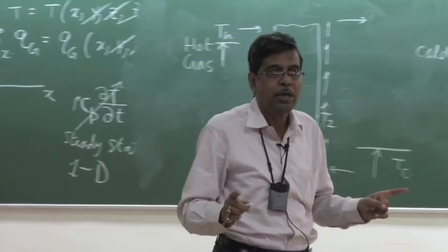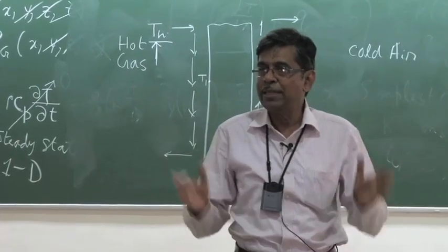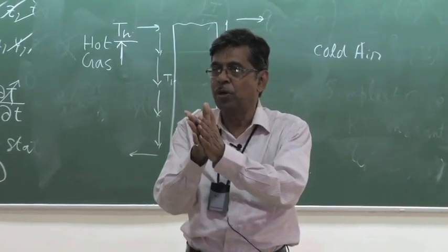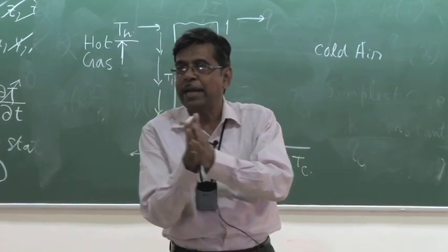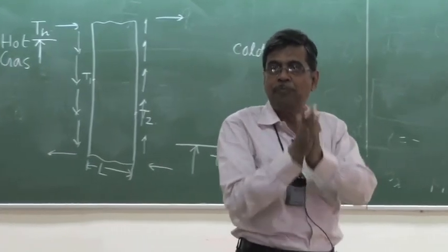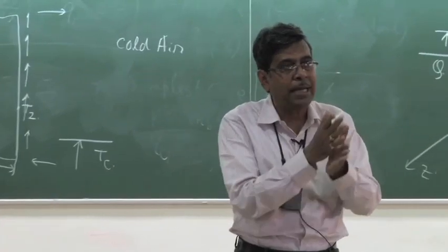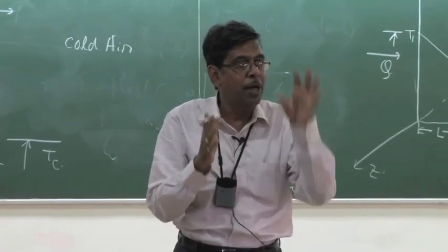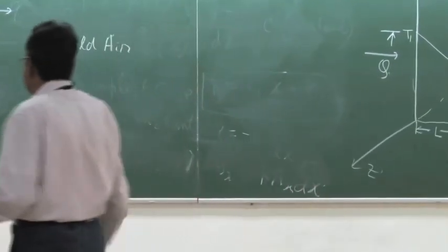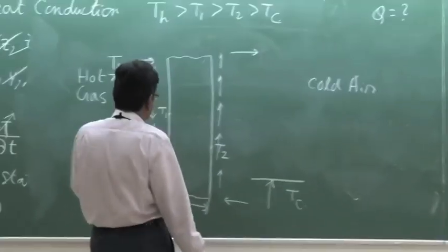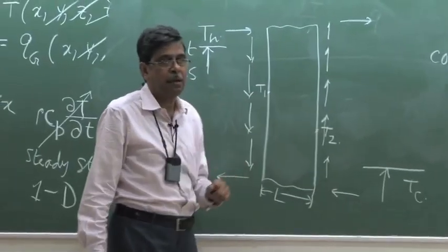And this flow, even in the absence of any forced flow, is what makes this different from conduction. That's why I told you, in a fluid medium, when there is a solid adjacent to a fluid, the fluid cannot be kept stationary. So there will be flow. That may be a forced flow or a natural, buoyancy-induced flow, because of which this heat transfer will be convection heat transfer, different from conduction.